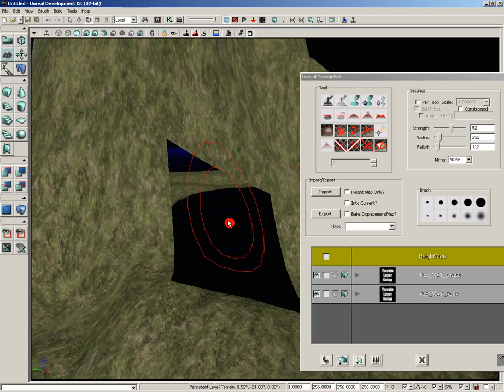You can go ahead and hide those away, and it'll keep things nice and efficient. Now, moving on from here, you have some texture controls. You can pan, rotate, and scale textures. Just watch out, because after you do this, you've got to recompile the texture to see the result. So it's not the most interactive tool in the world.